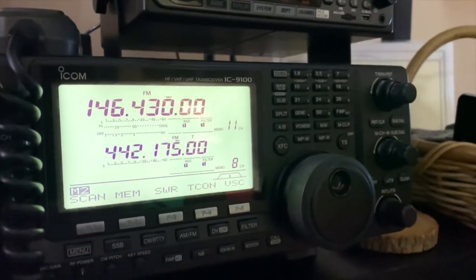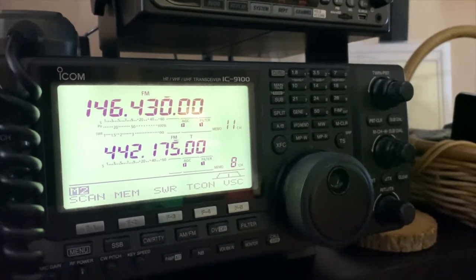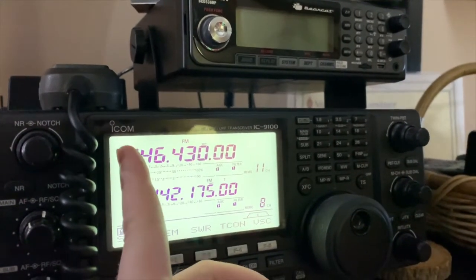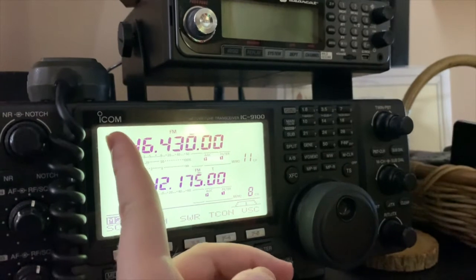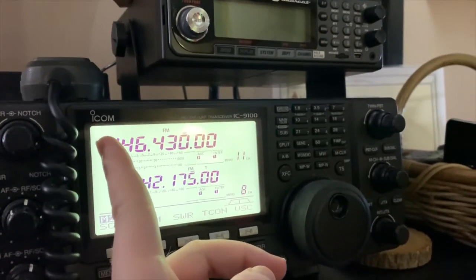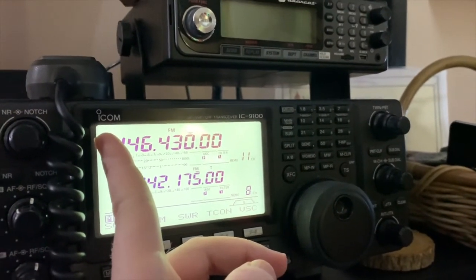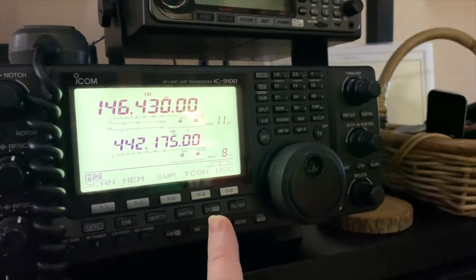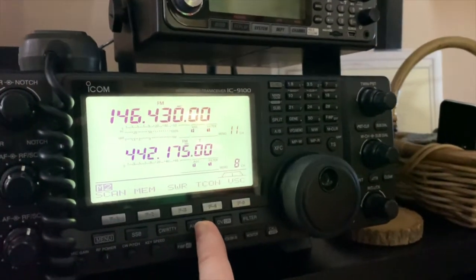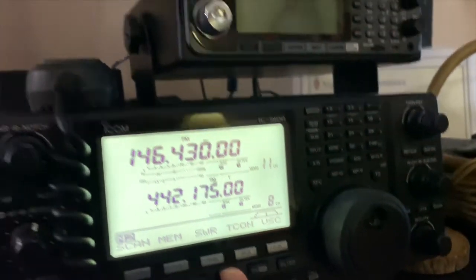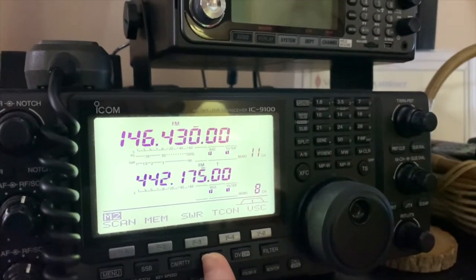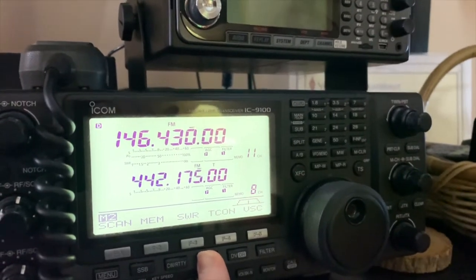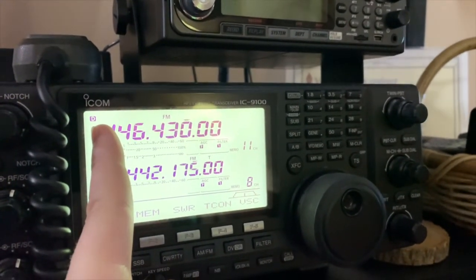The first thing you need to do is put your radio into digital mode, FM digital. Right up here where my finger is, there will be a D icon, and we need that. To get into that mode, you need to hold down the FM AM button until you see the D, and if you look in the far upper left corner, you'll see it appear. So I'm going to do that now. Press and hold. There it is. Now we have the D icon there.